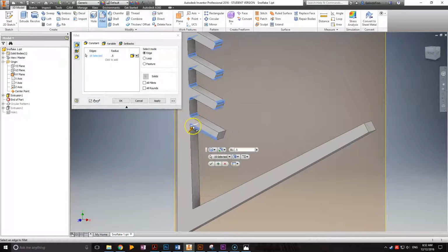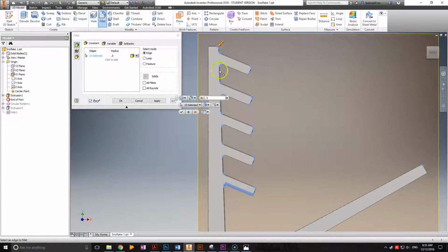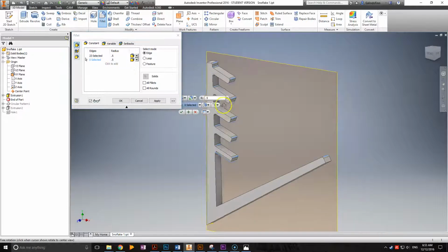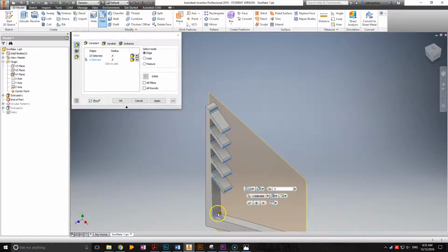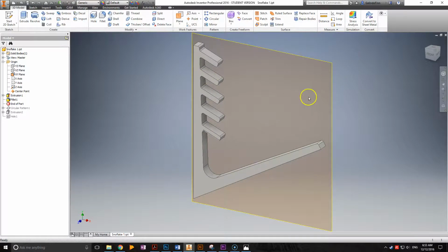However, whoops, I didn't mean to do that one. Because everything is going to be rotated around, remember not to do them on this edge, you want to just do the other edge, and they only want to be the ones that you can see as a curve from the front face. Then you can have a bit of fun with your shape. Now I'm going to also do this one, but I'm going to change the size of this one. I clicked the click to add option, so I could add a few more. I'm going to change that to 3mm, so you can see you get a nice big curve. And then I'm going to click tick, and it will apply all those fillets, as we call them.